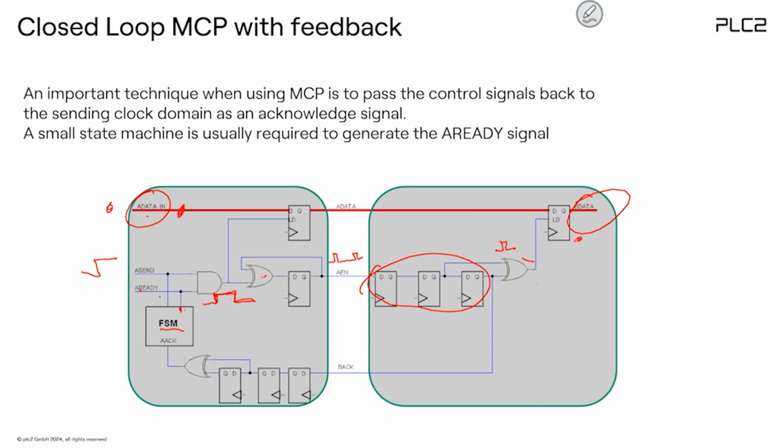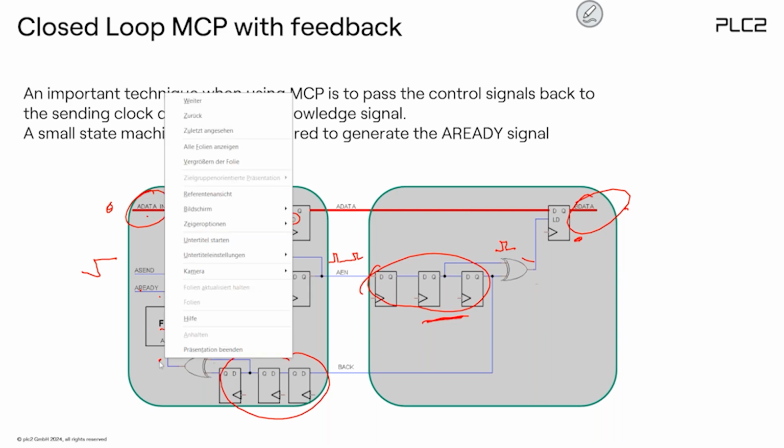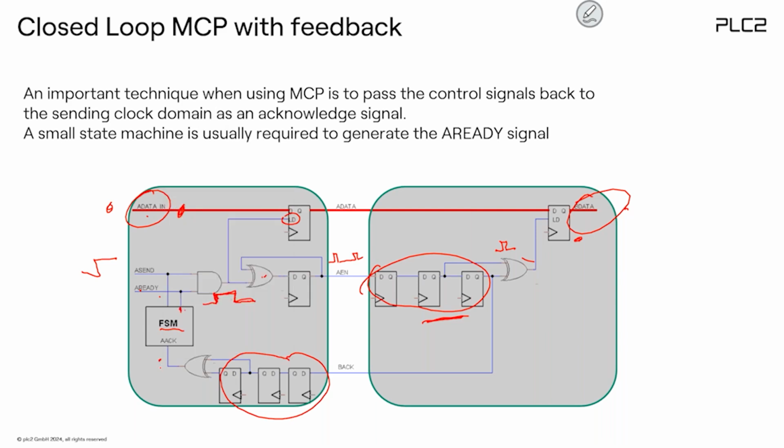Also, because we just take this data, it is loaded here. And this is 2 cycles later, or even could be 3 cycles later, the data captured here. Because we just captured the data, we have the feedback. Now we synchronize again, and we say to the state machine, yes, I acknowledge everything is okay. And because everything was okay, the state machine says, well, I'm ready again.